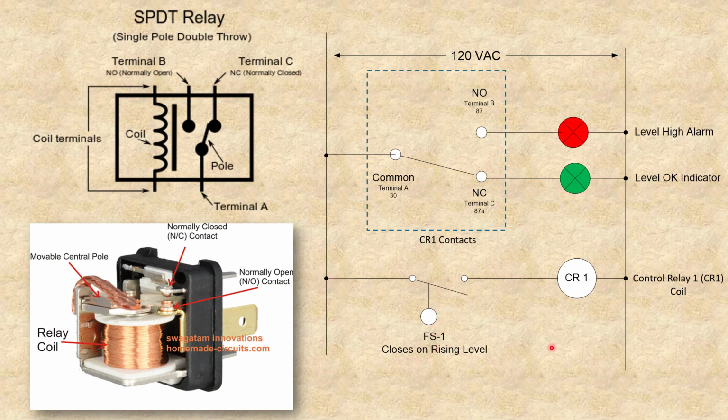the level in this tank, this is a float switch, the level in this tank is at a level that we'll just say is suitable. And because of the position of the float, and the switch that's operated by the float, this is de-energized. And because it's de-energized, the normally closed contacts are connected to the common terminal, shown as terminal A here. Again, this is all part of that assembly, and this actually is in this assembly too. You see the coil and the contacts.